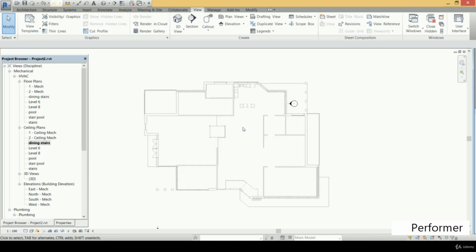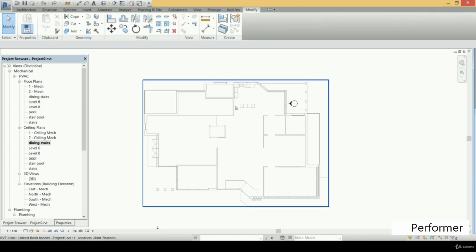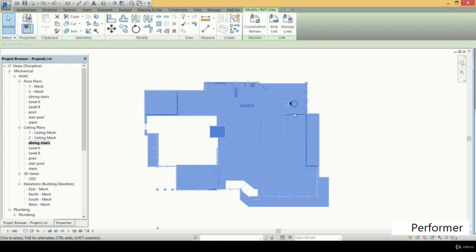And now the first thing we need to do is to pin our layout. And the pinning operation means that we will fix the layout at its original position to prevent shifting the layout from its position. As when we are working on the project, we may drag the layout from its original position with respect to the original coordination. So to do that pinning operation, we easily go to the Modify tab. So let's go to the Modify tab, and then we select our design file. Left-click.